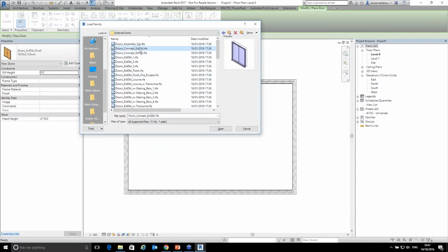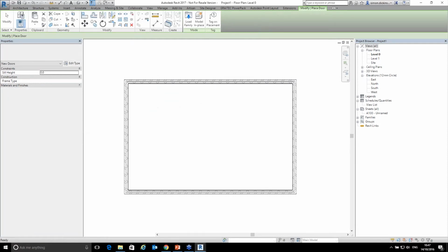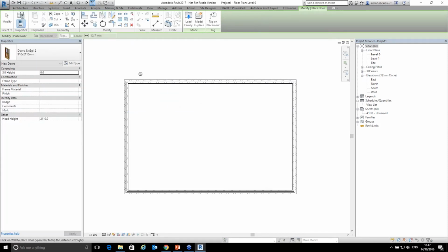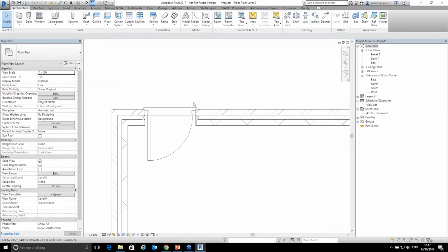So we can start to have a look at what the thermal properties are of a brick. By adding the materials in here as well, I've now got the ability to look at what the overall thermal resistance is for this particular wall construction. Resistance doesn't mean too much to most people, but what most people do recognise is when we look at the heat transfer coefficient, otherwise known as the U value.